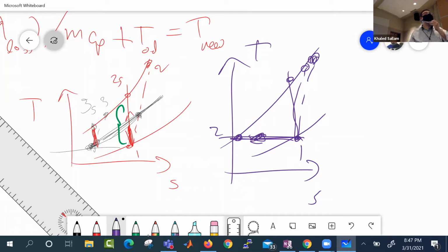So in an isothermal process, by the way, the work is equal to the Q. The work that you spend is equal to the Q. That's why the temperature does not increase. Whatever compression work you put in is equal to the heat transfer that leaves the compressor.